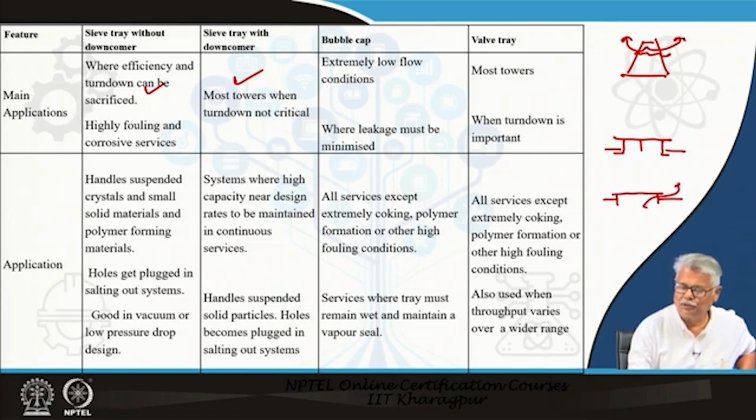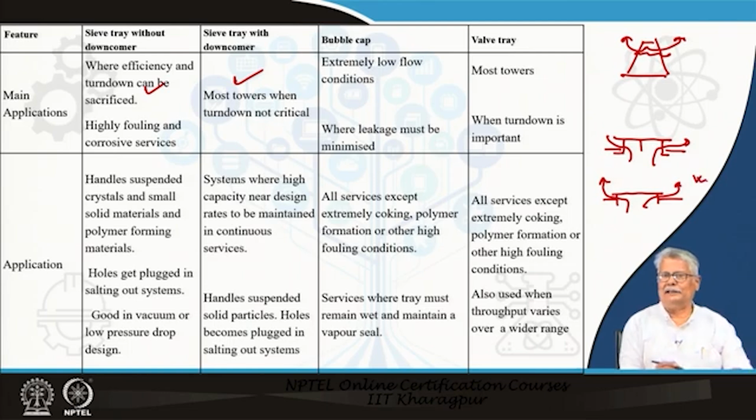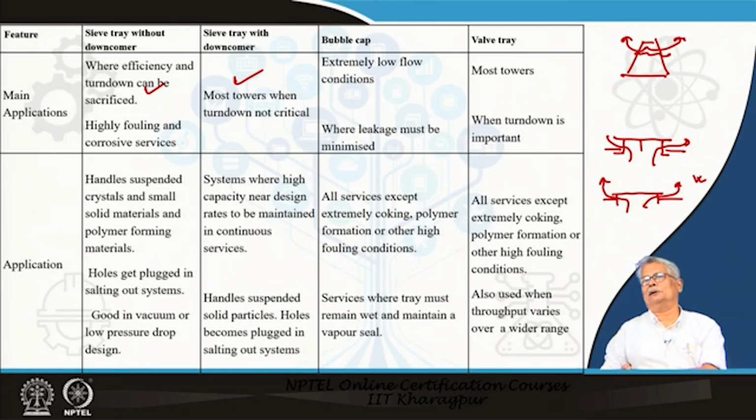So, the area through which it comes out is also lower when your vapor flow is less. This allows almost the same quality and the same size of the bubbles being formed and keeping its efficiency fairly constant over a large operating range.